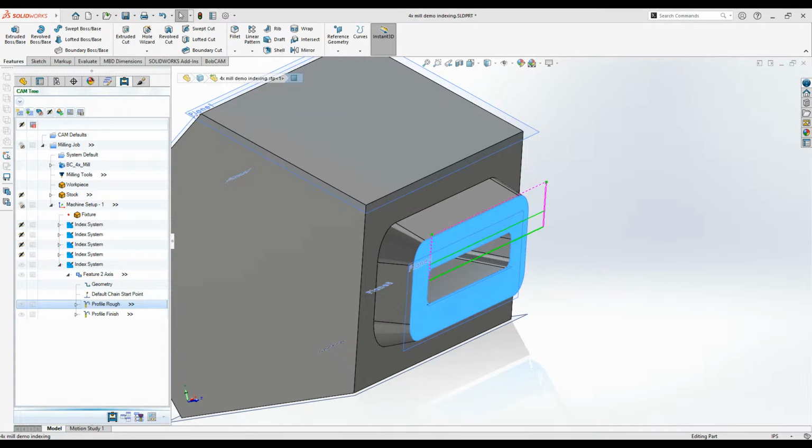Yep, I agree, Mark. Saying the side cutting makes a nicer finish. So those are the options of how to create using the side of the tool, making a nicer finish with that. Using the side of the tool profile cut to finish anything along the part file there with the 4-axis with indexing.